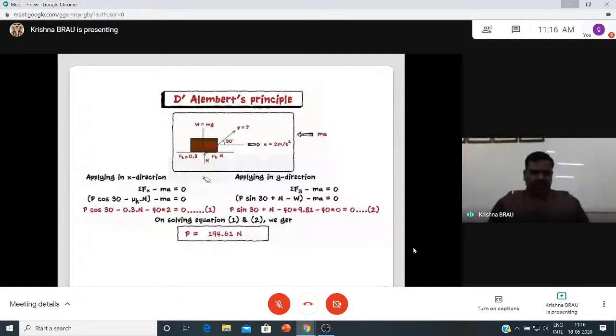and that is one equation, but the horizontal equation is if I can apply Newton's law and D'Alembert's principle. As per Newton's law, the equation is P cos theta, because force and acceleration must and should be in the same direction. P cos theta is equal to A, and frictional force, because this is the motion, frictional force is in this direction. This is the direction. That's why reaction is equal to mass into acceleration. That is Newton's second law.